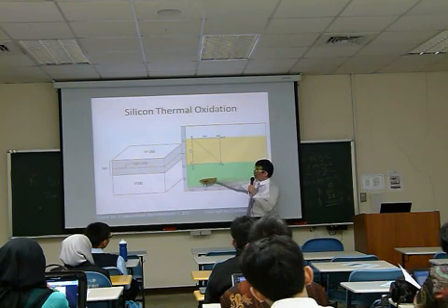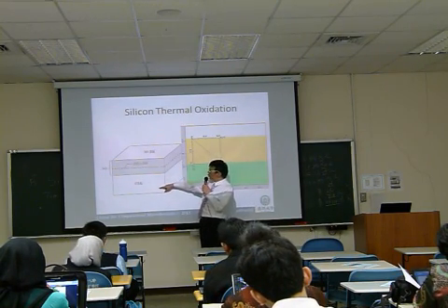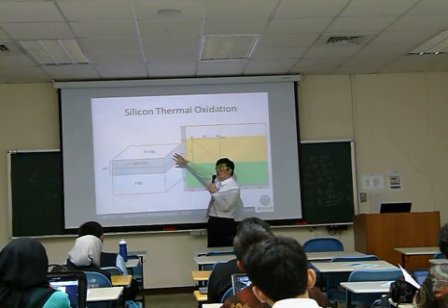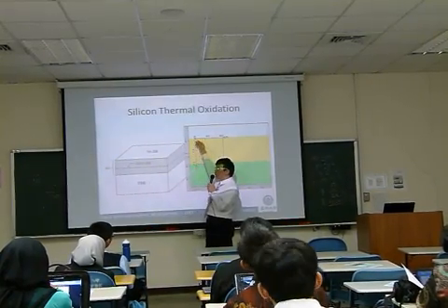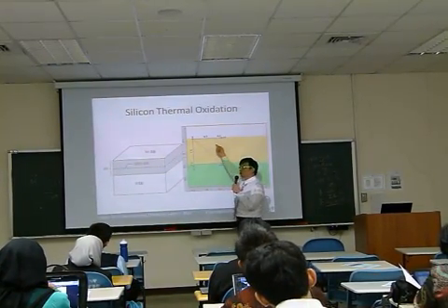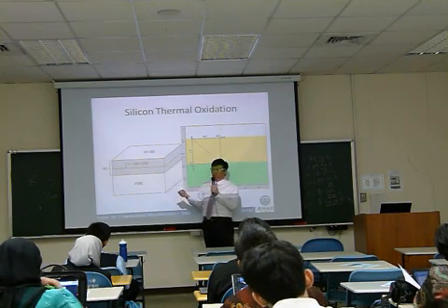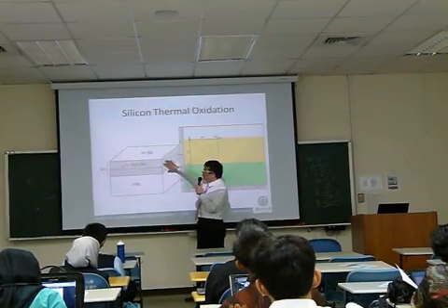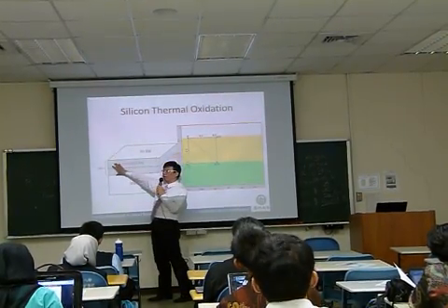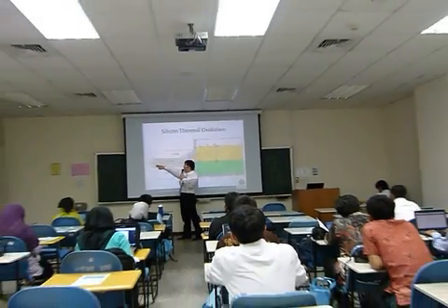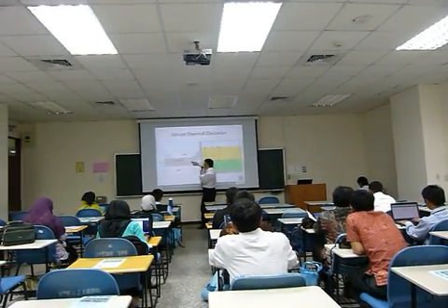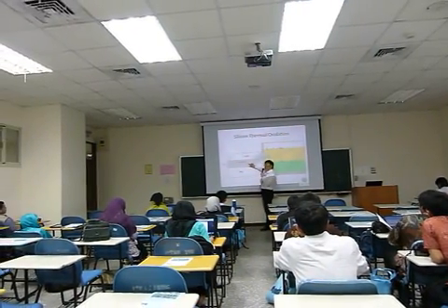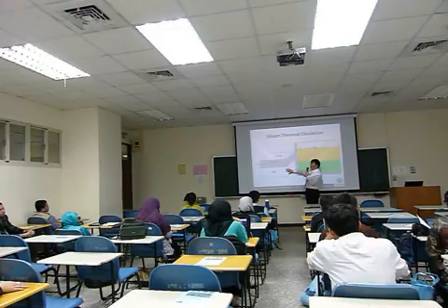Okay, so in reality, we take the silicon wafer and use silicon thermal growth. For silicon growth, we use a furnace and put oxygen in, so it goes into the reaction. This can get silicon dioxide. At the initial interface, when we grow oxide, it releases some silicon. So this is the real case.